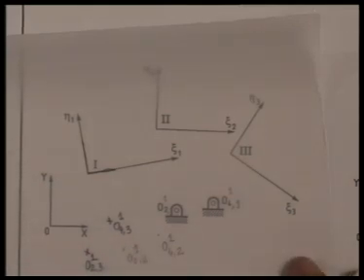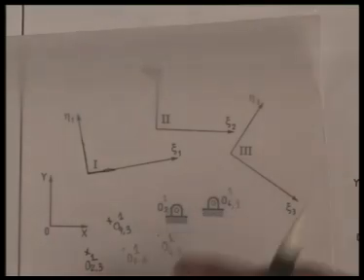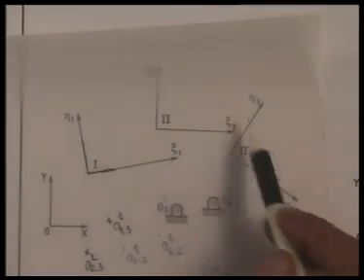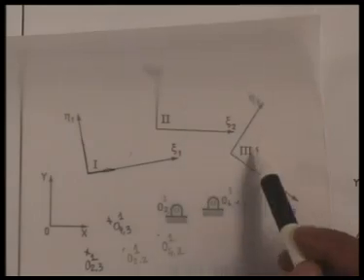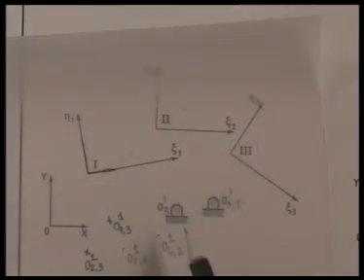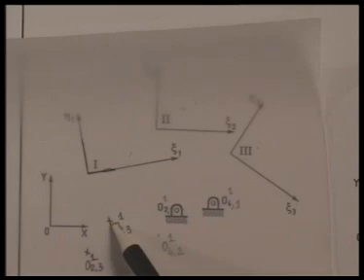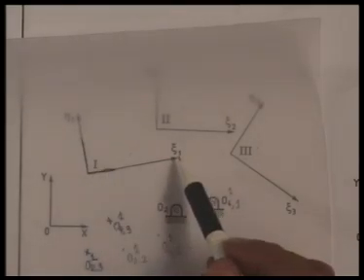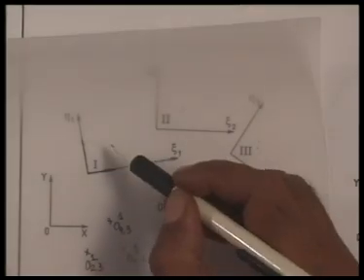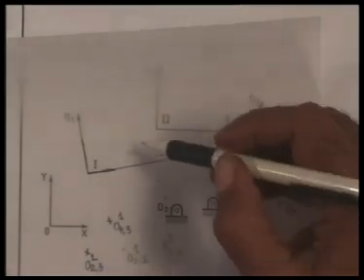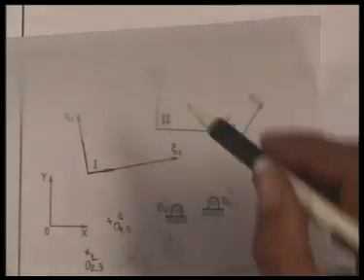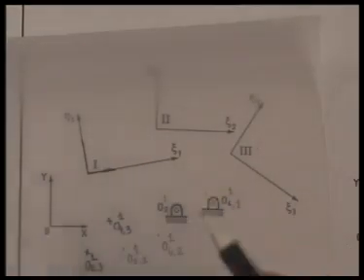So if we fix the coupler and allow the fixed link to move, the same relative configurations as given by the moving coupler with respect to the fixed link, then the fixed link moves such that O2 goes from O2,1,1 to O2,2,1 to O2,3,1. Similarly, O4 goes from O4,1,1 to O4,2,1 and O4,3,1, by holding the coupler fixed. If the coupler is fixed, then A does not move, A is fixed, and because the A, O2 distance is the same, O2 moves on a circle with A as center.